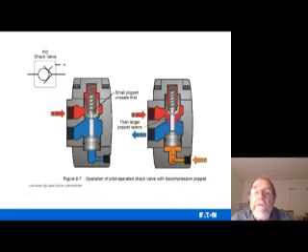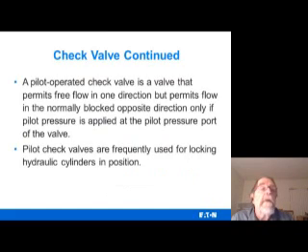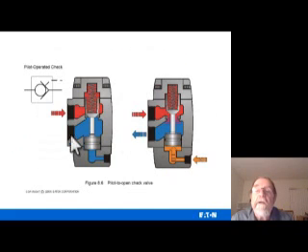And there you go again with a different type of pilot. It's not, the fluid's coming in, but it's not doing anything because it's locked. But if the pilot comes in and opens it, and we go back to the other one, let me show you something. Here you get pilot voltage fluid coming in. Right now your regular flow is blocked. Once the pilot opens this up off the seat, it moves this up and lets the fluid come through this way.